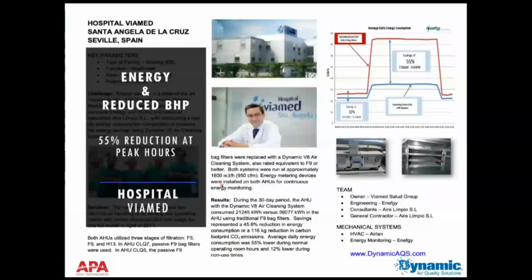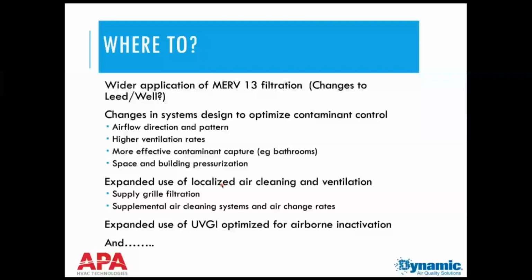So those are some of the things we can do. I'd be interested to get some of your input. I mean, I'm talking to people looking at things. I can think of some places that we're going to need to go in our industry. I think wider application of MERV 13. It'll be interesting to see if LEED and WELL go back to MERV 13s throughout. Remember, the early versions of LEED required MERV 13 filtration throughout the building, and now it's just required on systems that see outdoor air. Obviously, if you're trying to control an airborne pathogen, you'd probably want to change that back to 13 inside too.